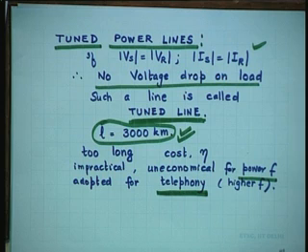Just as a passing reference, let me tell you, in ships and airplanes, we have 400 hertz. Even that is not sufficiently high. Why have 400 hertz? Because weight becomes a weighty problem, an important problem. You do not want higher weight on a plane. So, all the equipment, all devices, even your power plant, if you have that, will be of 400 hertz, so that the size is small and the weight is small.